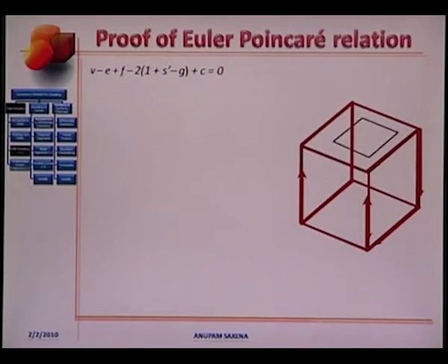If I introduce a boundary component, I open up this top face, and of course I'll have a loop here, because of which the number of faces will decrease by 1, so that the total number of faces for this polyhedral solid will be 5, but the number of loops will be 7.